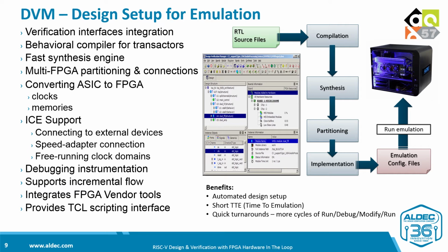Then, in case of large designs that don't fit in a single FPGA, the netlist can be partitioned automatically into multiple FPGAs. If your design has ASIC-style gated clocks, they will automatically be converted to clock enables, and the user can also map non-synthesizable memories to FPGA or to external or onboard DDR resources.